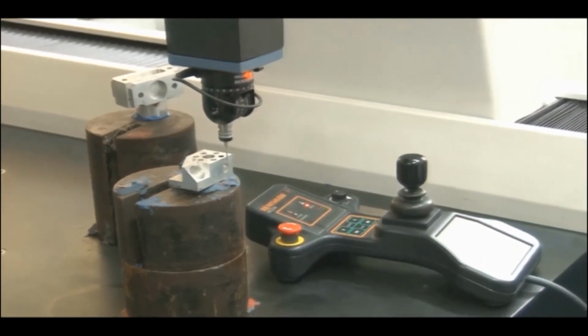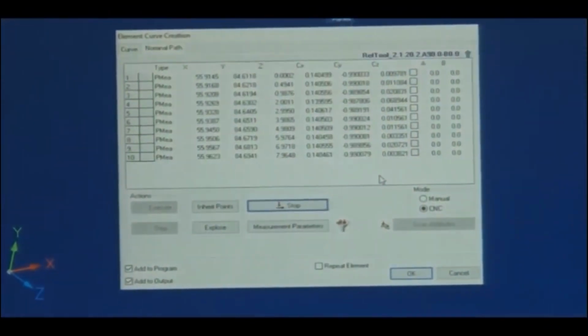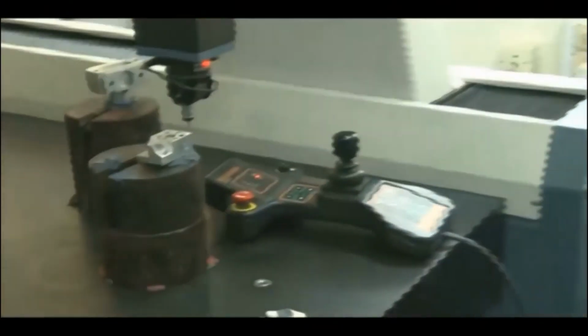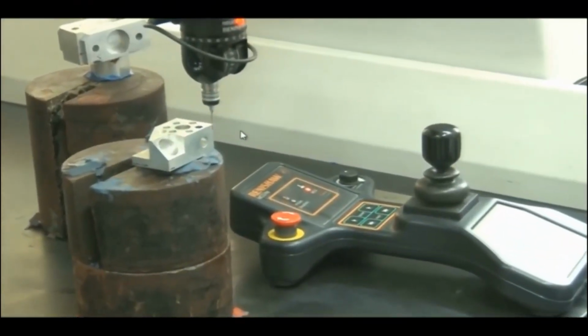Okay, at each 1 mm, it is recording the points here. You know, the points are being added here. It will keep recording unless it exceeds, like in this direction, in the x direction, 500 is the length it can move, 500 mm. So it can keep moving up to 500 at all, unless this workpiece finishes here. It wouldn't find anything here.